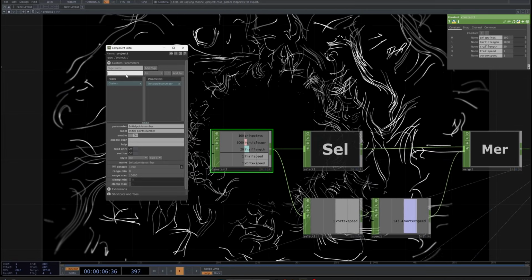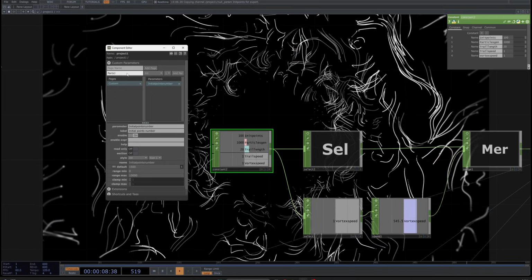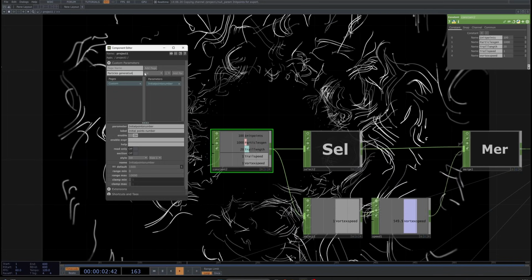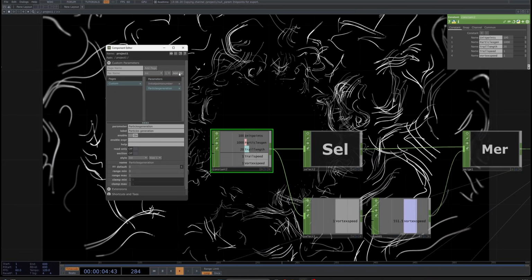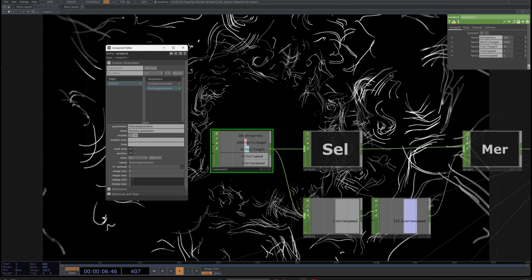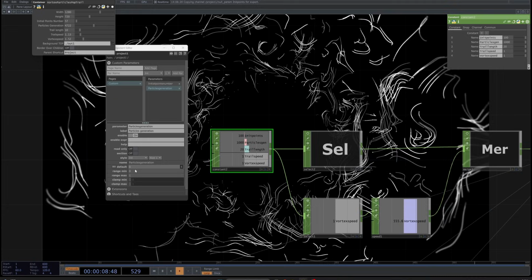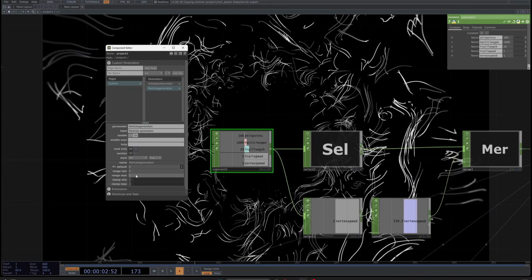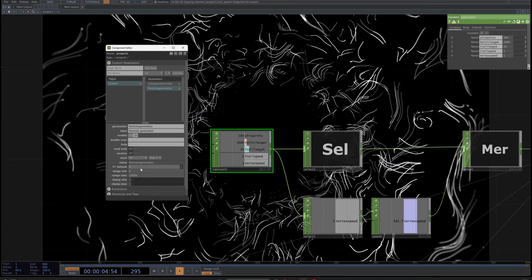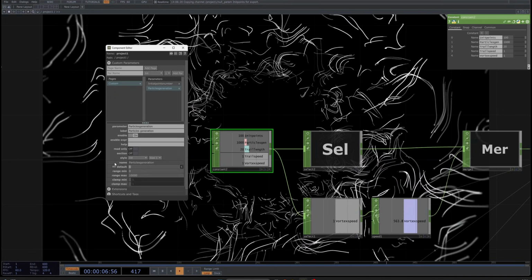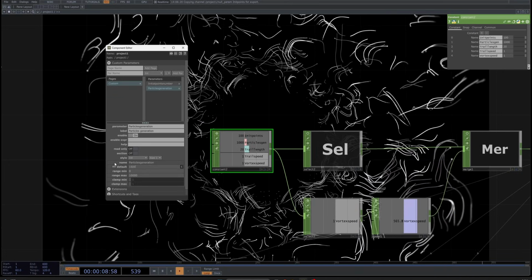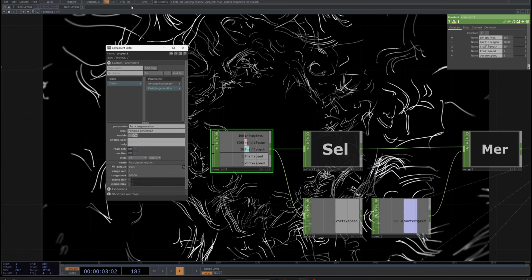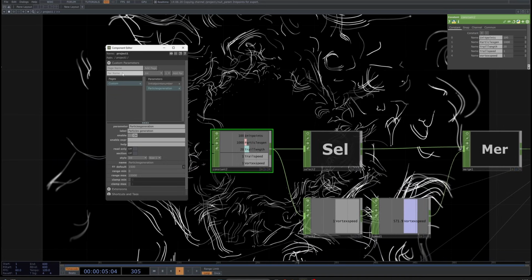So then particle generation. I'm going to call it particles generation, and it's going to be int as well, add parameters, and for this one same, range minimum 0, so it won't generate anything, and range max maybe something like 10,000, and again I'm going to use as default 1500, but you really have to check the limit on your system and see if you have dropping frames or if you can go further.